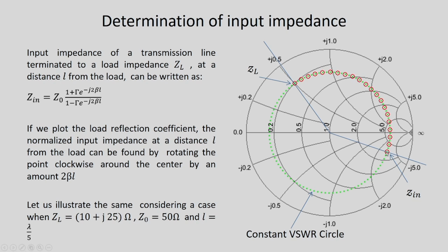So, you can now read out the impedance at this point. It is closer to a circle around r equal to 3, and j approximately, which in the actual Smith chart you can read out. In that way you can find the normalized input impedance and then multiply it by Z naught, that is 50 ohm, and you get the actual impedance seen at this point.